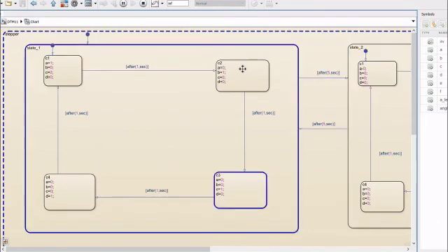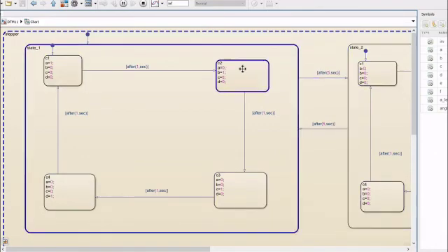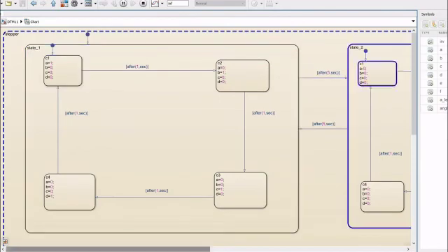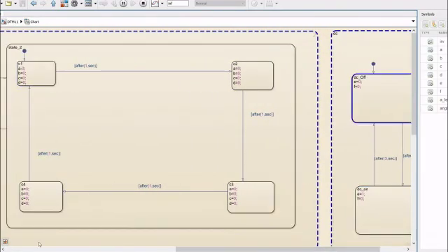So we can use the stepper motor to load the disc into the launching unit. During the loading of a disc from the disc holder into the disc launching unit, the stepper motor rotates stepwise to complete one revolution of the stepper motor. After completing one revolution in 5 seconds, the stepper motor switches to off state, which is this state.